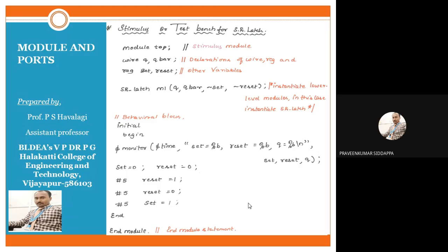If you have a loop, then we should use the always statement. If you want to execute only one statement, then we should use initial. Whenever we use any new syntax, we should enclose it using one begin and one end. Remember it.